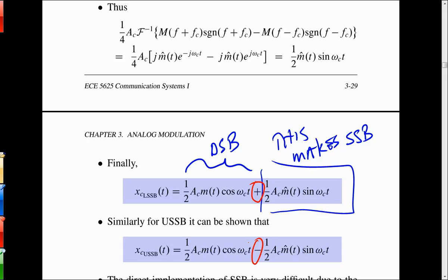It has a parameter that you enter into it, so you'll just enter a parameter like a +1 or a -1. I forget how I specified it. That will do that, and then you can use a spectrum analyzer tool in software to look at the output spectrum, and you'll see that it will flip from upper to lower. Now, it won't be perfect, because the filter is a finite order filter, but it will definitely switch it.